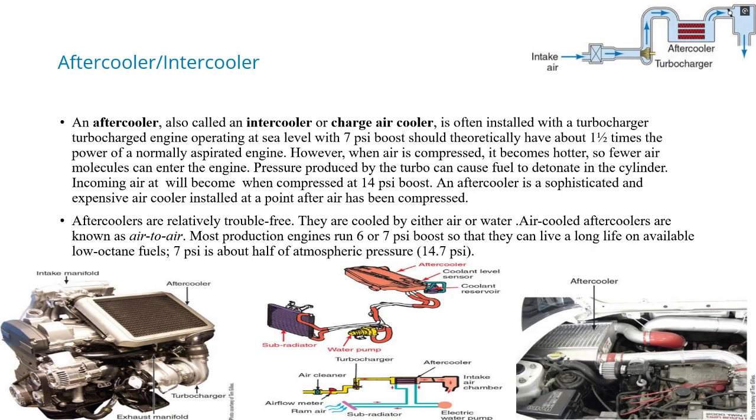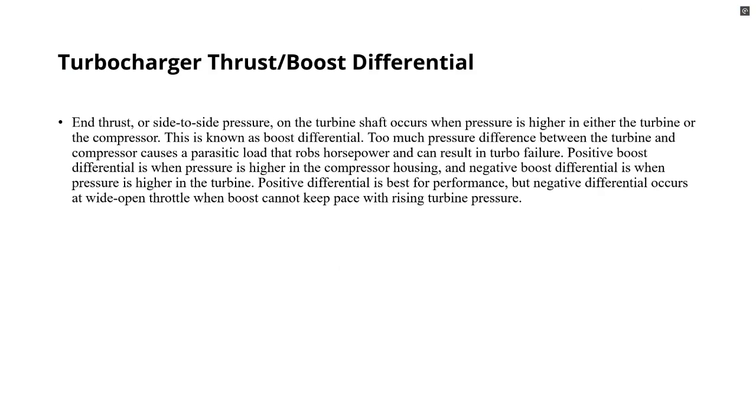Aftercoolers or intercoolers are installed to cool compressed air from the turbo, preventing detonation and improving power. Air-to-air and air-to-water cooling methods are common. Too much pressure difference between the turbine and compressor can cause parasitic load, reducing efficiency. Boost differential must be managed carefully for peak performance.